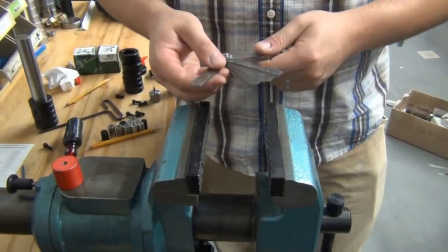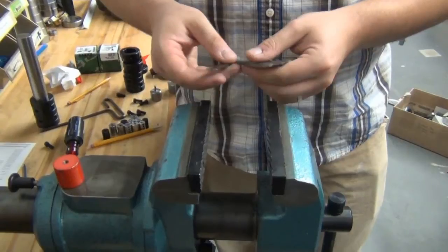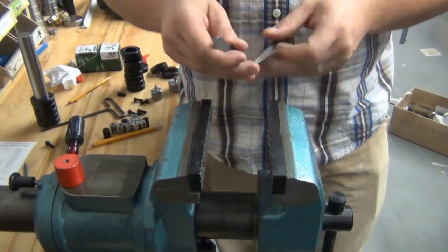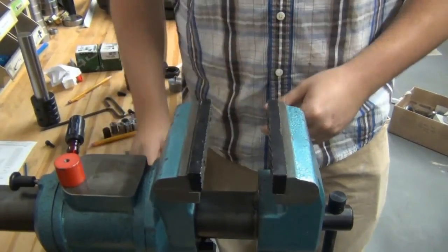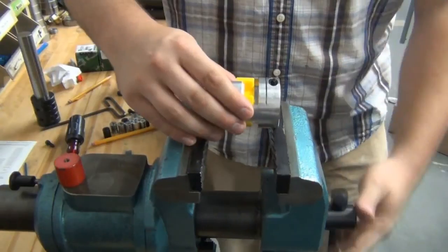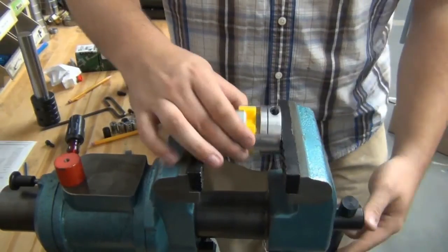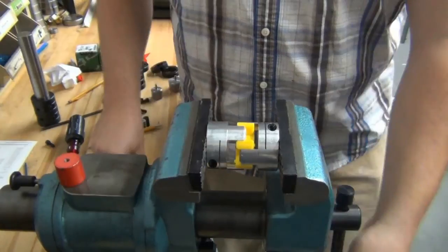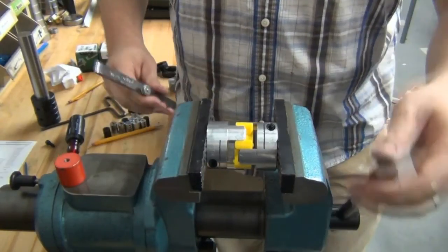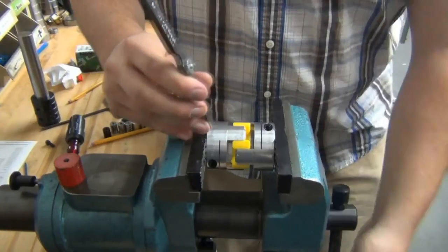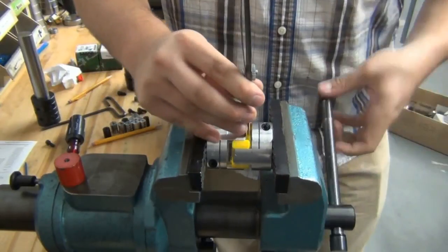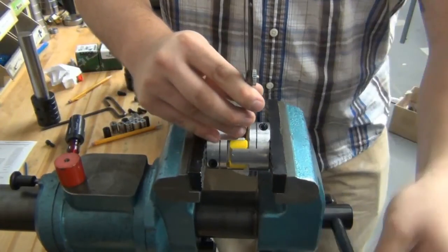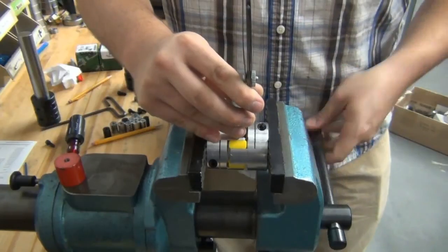All right, this is a video. To install the jaw coupling, we're going to need a feeler gauge which is set to the correct size, two hubs and a single spider, and a compression device. Place the semi-assembled jaw coupling into the compression device and tighten until the nubs on the spider are touching the base of the hubs. Use the feeler gauge to maintain the gap between the hubs to prevent metal-to-metal contact.